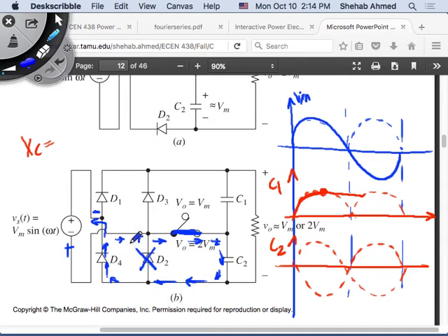Okay? So we'll go back, charge this capacitor, go back through D4. In the second half cycle I charged, so initially it's discharged, and then I charged this capacitor in the second half cycle. And then the full output voltage is the sum of the two as well, right? So then the full output voltage will look like, yes.